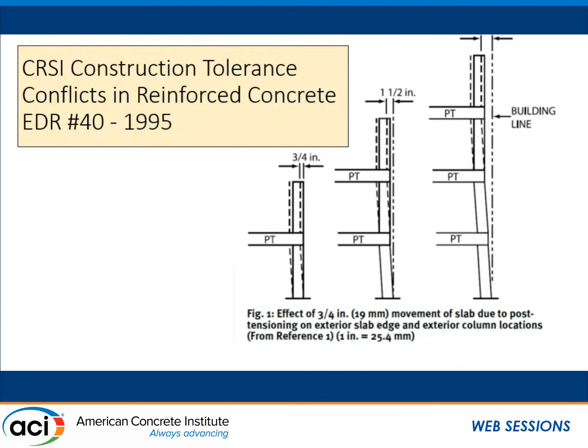Now, I know some contractors say, I'm not worried about that. I lean my columns backwards. I say, well, how much? Well, I don't know, I make a guess. I think I'd ask before I start leaning them back and deciding what I was going to do. But we end up with problems on the edges because of these goofy curtain wall installers. They think their curtain wall or facade is going to be straight, level, flat, whatever we want to call it, true. I love that word, true.